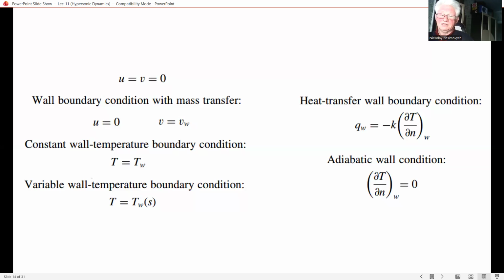As a final note in this module, we observe that the non-dimensional Navier-Stokes equation, in the limit when the Reynolds number goes to infinity, reduces to the non-dimensional Euler equation. This supports our earlier statement that an inviscid flow can be thought of as a limiting case of a viscous flow when the Reynolds number becomes infinite. Okay?